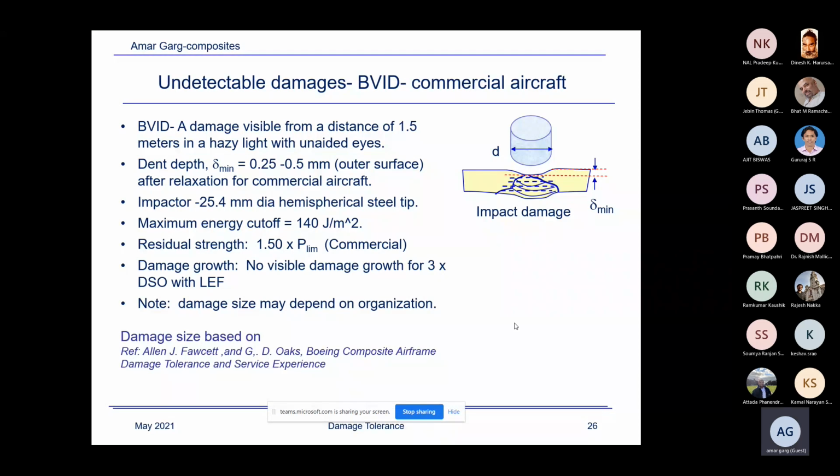For composites, there's no inspection plan that way. You don't consider the crack growth rate for composites; it's not considered. Yes, because there we only consider the S-N approach, only the stress life approach, the safe life approach.